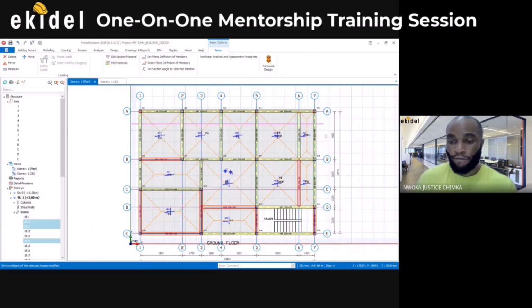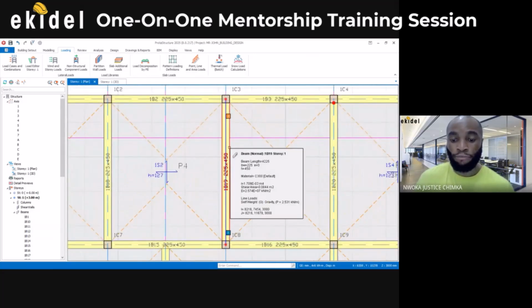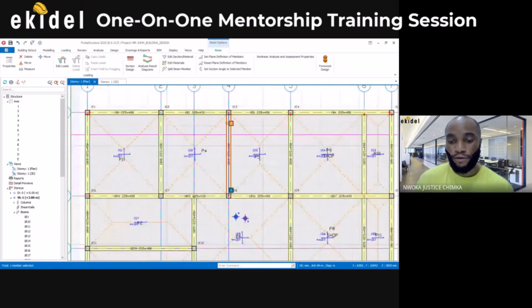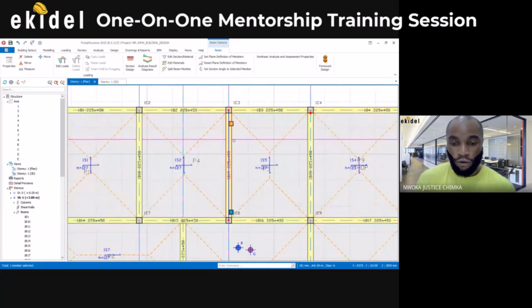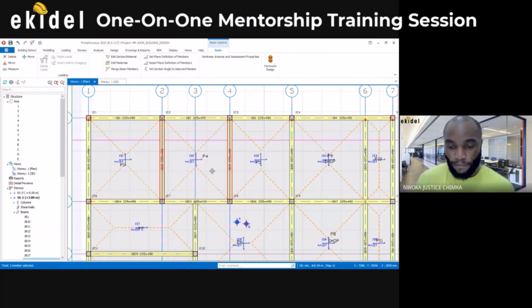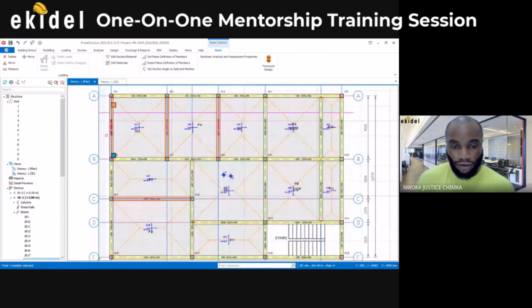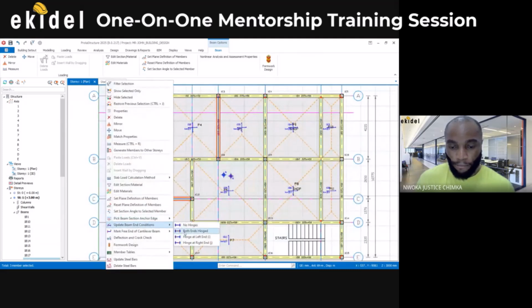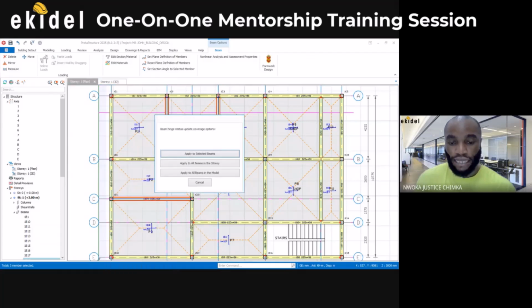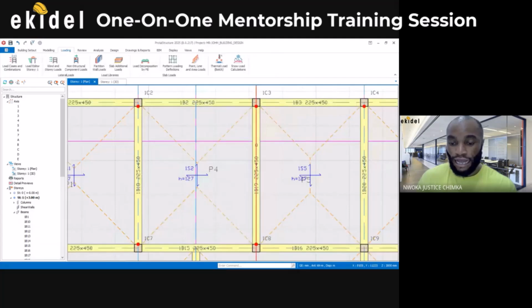Now, once you've done that, we need to confirm all the ends. Now, this one has both ends because both ends are free, right? So I'll have to hold again and select all the ones that have both ends. This is both ends too. I'll then right click and select. You can see it here, both ends. So I'll click here and say both ends now. I'll say apply. Okay, so you can see that they are all both ends now.